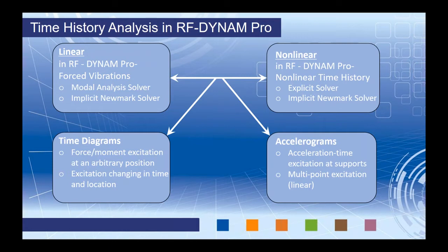Load cases define the location and the excitation of how this load will be applied according to the time diagram. So for example, we would apply nodal loads, member loads, surface loads, and many other options within these load cases to determine where exactly this excitation will take place. The combination of several independent excitations is possible, and the excitation can also vary over time and position.